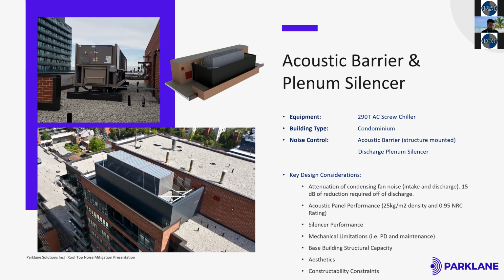Okay. Silencers can be designed to make the air pressure loss lower or whatever it comes out to be. In this instance, the pressure loss was 0.25 inches of water, but we can always make the silencer so that the pressure loss is lower. Before one goes about designing this, the mechanical consideration would be one of these items.